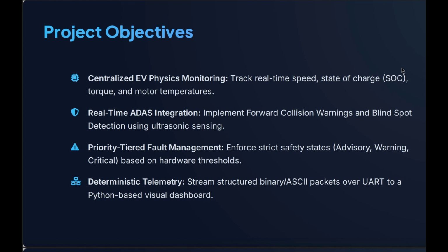So, the solution. To solve this, I have implemented the central EV ADAS dashboard system, which provides real-time monitoring of the speed and SOC range alongside ADAS collision and blind spot detection. It features a tiered alarm system, live telemetry via UART, and a dynamic Python dashboard.